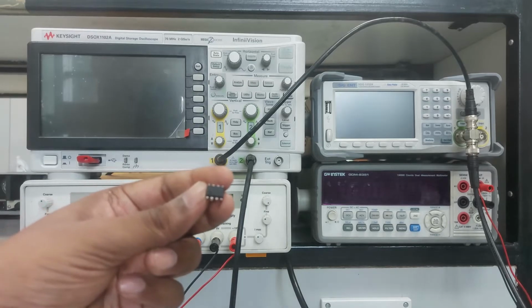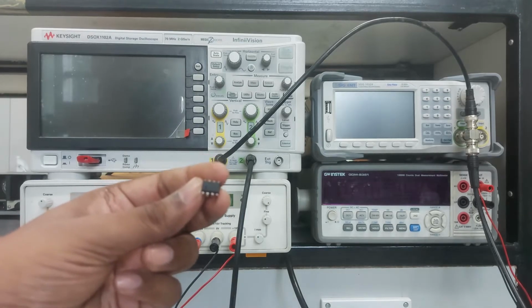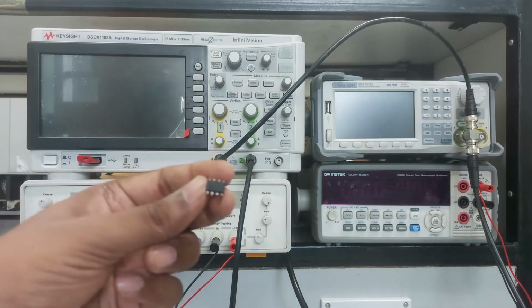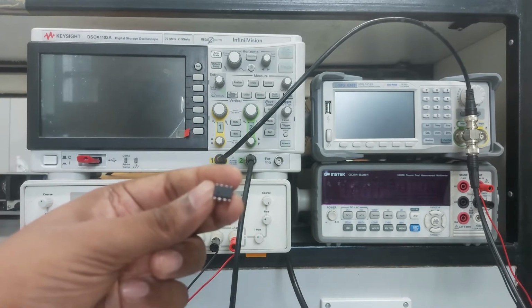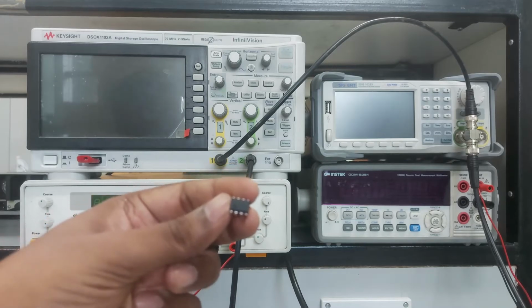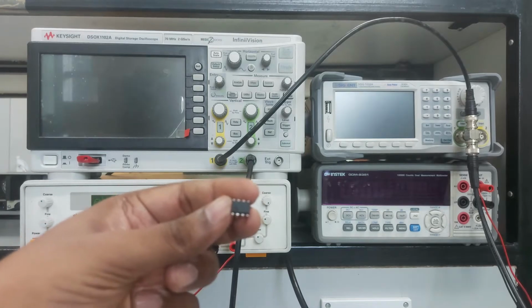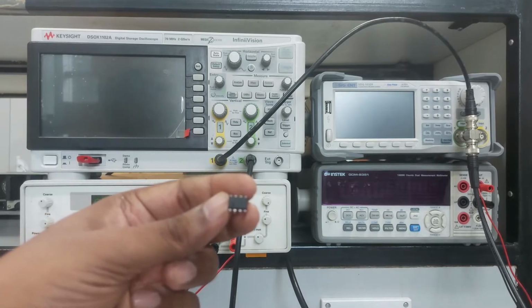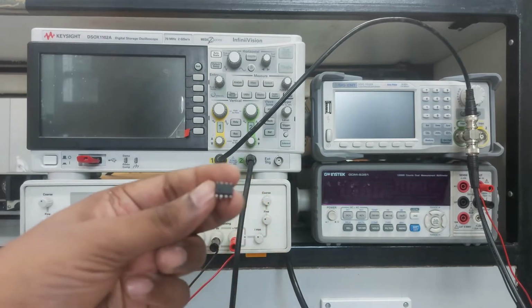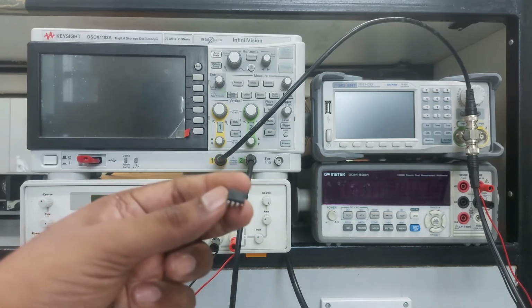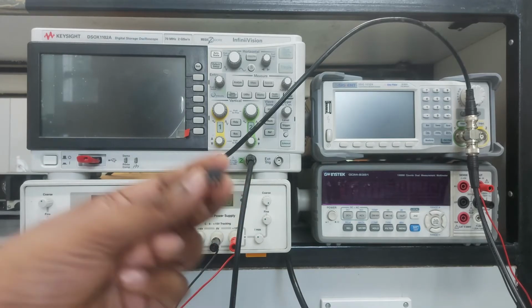We have to nullify it by adjusting some DC bias voltage, so that without giving any input we should get output 0, or if we give the same input at both inputs, output should be 0, because we are getting the difference of inputs, multiplied by the voltage gain. So if the input is the same, output should be 0. So we will offset-null the op-amp before starting the experiment.